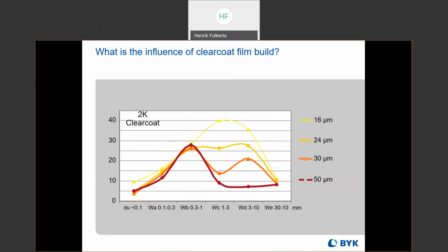So if it's a smaller scan length, maybe you have to do more of those in order to get the same repeatability of a longer scan length with just a few. And it's a pretty quick scan, so it won't kill you in terms of time. It will just add maybe a half a minute more of measuring time.